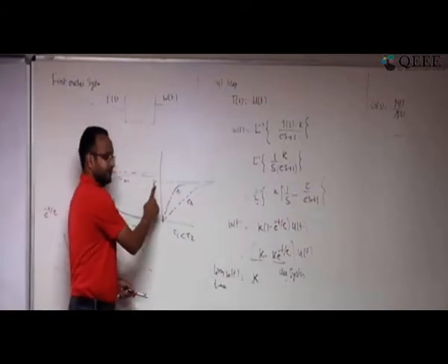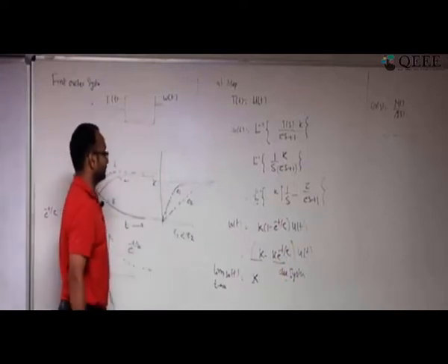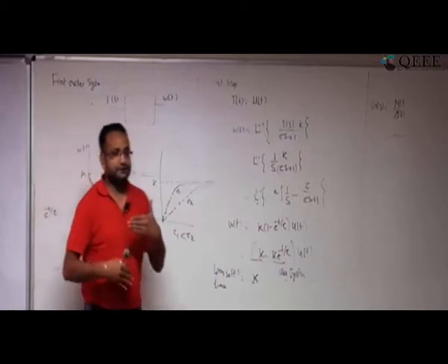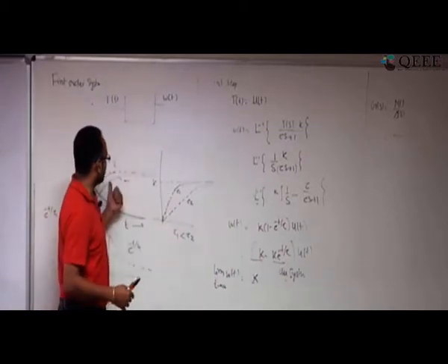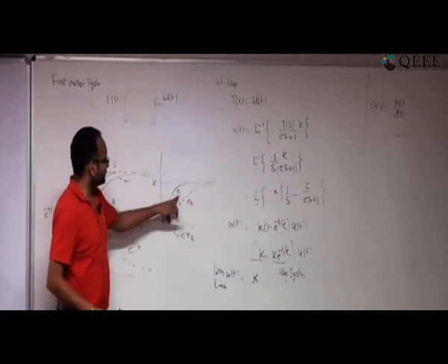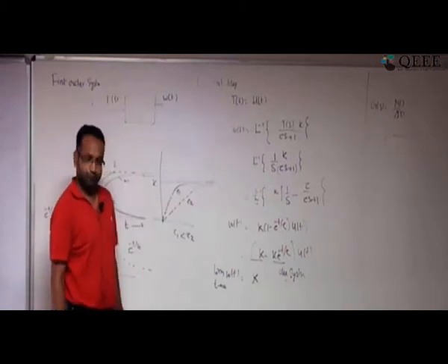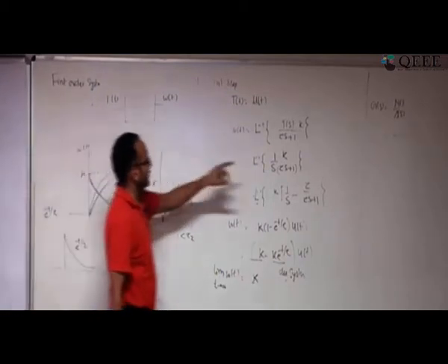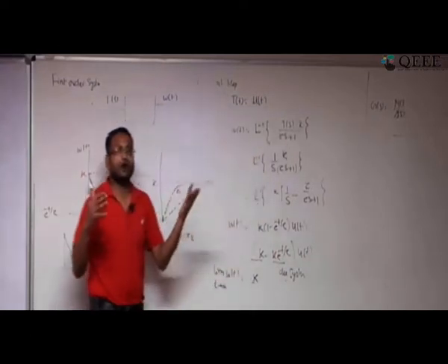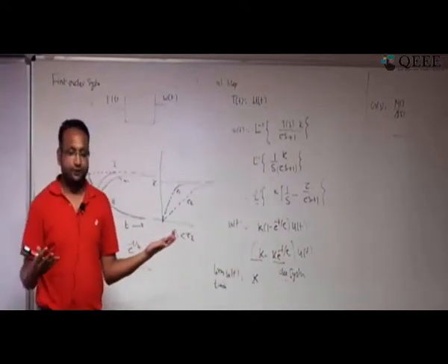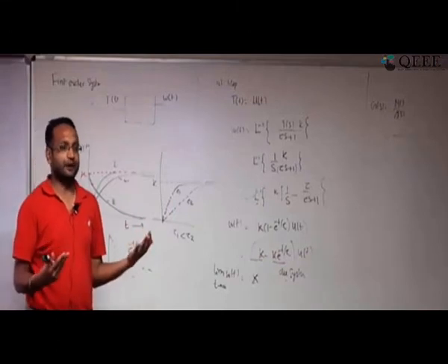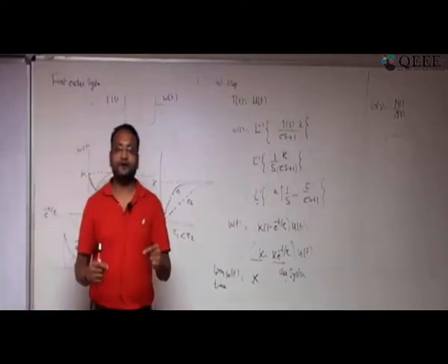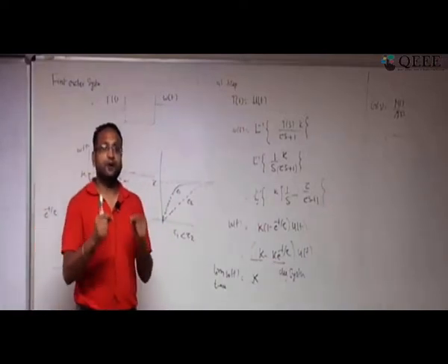And k is the steady state value. It is not playing any role in speed. So to understand whether your system is fast or slow, the time constant plays the role, and you want this time constant to be smaller. For a first order system, two parameters, k and tau, play a role, which we call the characteristics of the system. So tau has to be as small as possible. If you look at the example of your electrical circuit that I talked about, the transfer function is 1 by RCs plus 1. So what is the tau there? RC.